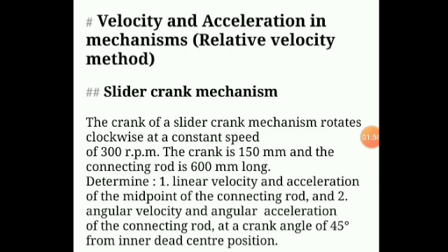So first and foremost, I hope you know that we have to draw the space diagram with actual measurements. Then using that we have to draw the velocity diagram, and we have to draw the acceleration diagram. So before that we should know what the given data is. So we'll move into that.